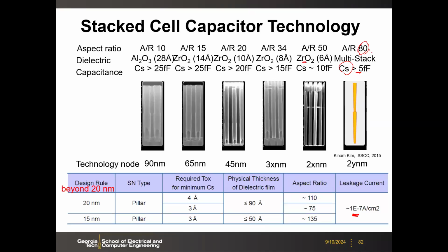So next lecture we talk about the DRAM cell capacitor, and here this is a summary. I want you to understand the cell capacitor is standing up with very high aspect ratio today. The aspect ratio is approaching like 100, and then we need to maintain the cell capacitance, let's say about 5 femtofarad, 5 to 10 femtofarad in that range, to have enough sense margin.